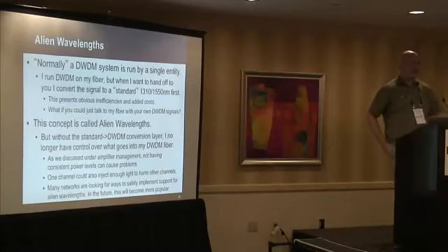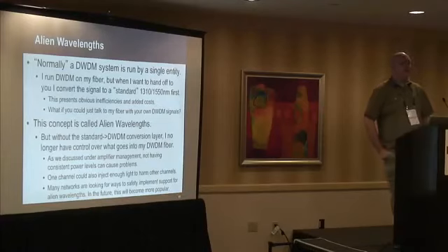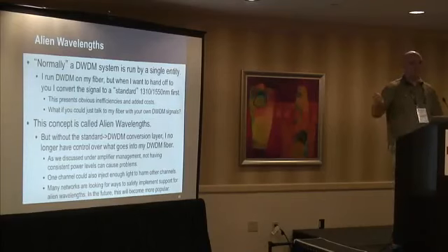What would happen if I could just go to the customer and say, hey, you get this frequency. You send your own colored light. That's called alien wavelengths. It has an advantage in cost, obviously. The disadvantage is if you're working with an amplified system, you need to know what is being transmitted into that, or the customer will go out and re-plug something else in the wrong way, and it will screw up the amplification. But if you're just doing a very simple unamplified system, you can absolutely do this, and there's people starting to look at it as a product.